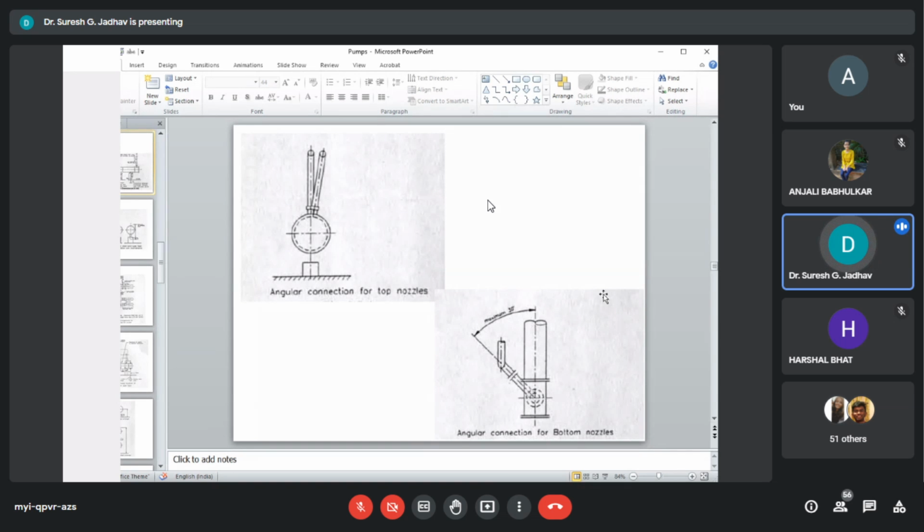Next advantage: corrosive liquid should pass through the tube so that only the tubes and the channels have to be made of corrosion resistant materials. If one medium is dirty and the other is clean, passing the clean one through the shell will make tube bundle removal and cleaning easier.